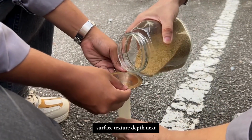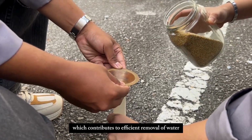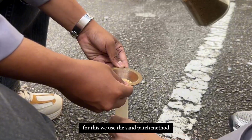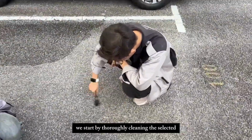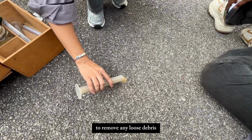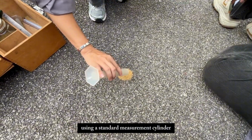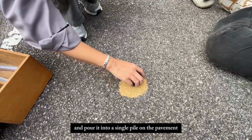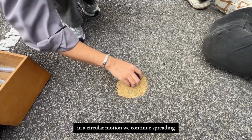Surface texture depth. Next, we need to evaluate the macro texture of the pavement, which contributes to efficient removal of water from the road surface. For this, we use the sand patch method. We start by thoroughly cleaning the selected surface area with a brush to remove any loose debris. We then take a known volume of fine sand using a standard measurement cylinder and pour it into a single pile on the pavement. Using a flat disc, we carefully spread the sand outward in a circular motion.